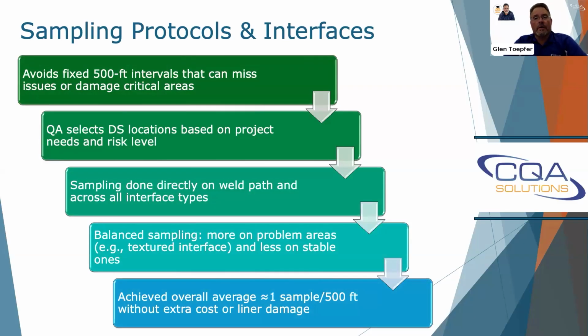Like at Palo Verde, when we were welding out there, the zero leak project, if I had an operator machine that failed, I would just reduce the frequency or target him more. I might reduce him down to 350 feet, but I'd increase each of the other operators 50 feet or 75 feet to help accommodate for that. So at the end of the day, I had the same amount of samples, but I was able to target the guy that I had a question with.